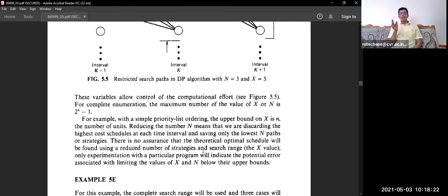From these 5, which is the least cost? One is 1,000 rupees, another is 2,000 rupees, and another is 3,000 rupees. If you commit all these 3 generating units to that particular dispatch, the cost might be least, and you can also manage that demand. To meet the demand with the least cost, you have to commit the least cost generators.